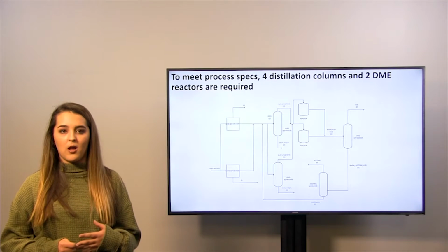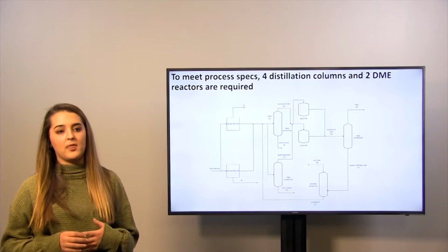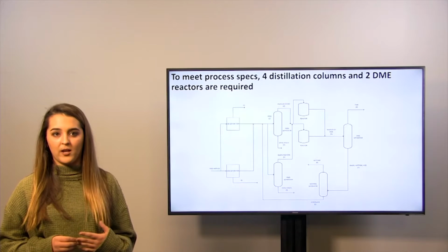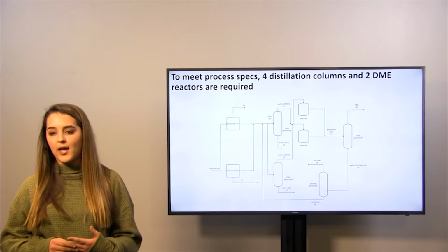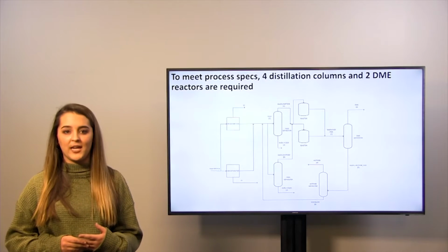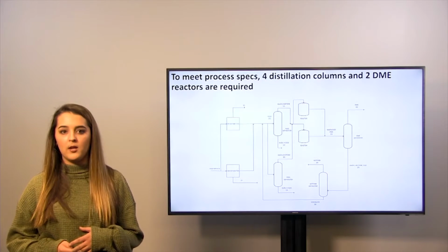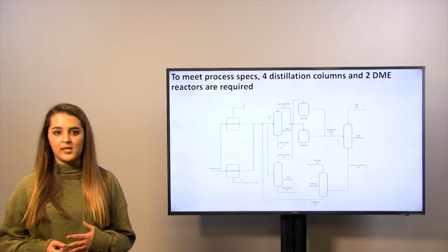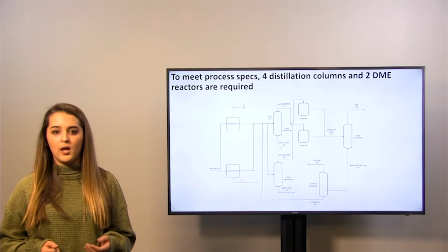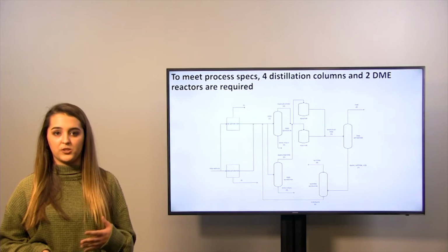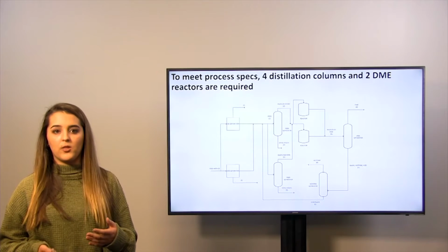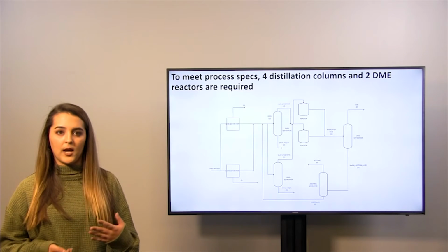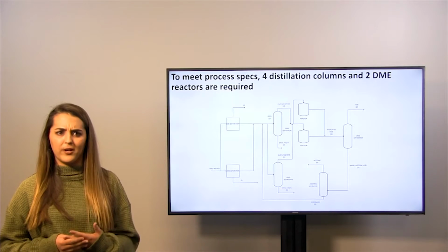The fourth distillation column will try to remove the acetone on the tops and the ethanol and water on the bottom to be recycled. However, the acetone and ethanol will create an azeotrope, which is hard to overcome. Throughout our research, we could see that water being added would help overcome this azeotrope, which is already present. Then the bottoms will be recycled into the feed to go into the first two feed separators.